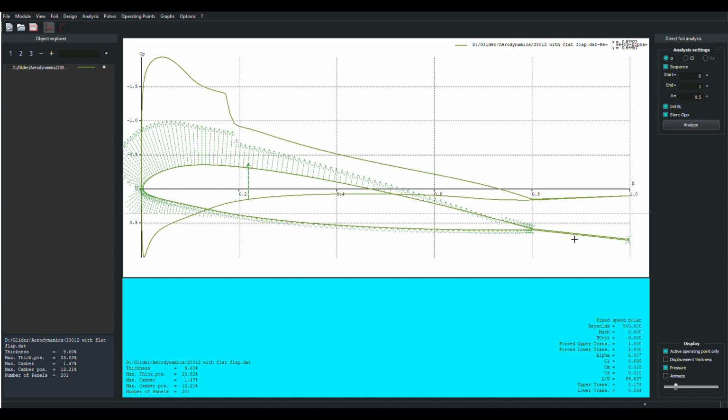So that's how it looks with just normal flight, and the controls are in neutral, nominally neutral. And we see here on the pressure distribution that it doesn't quite go flat because we're at an angle of attack and this is a flat plate back here.